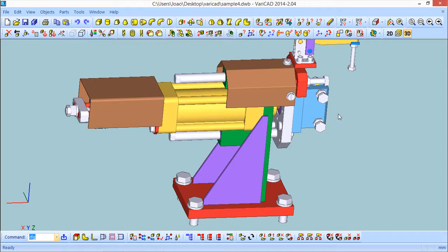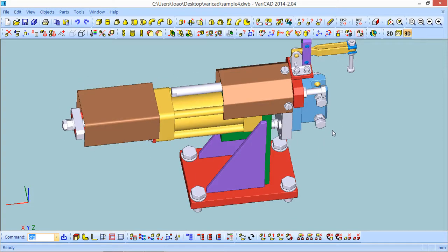The other thing we need to talk about in this lesson is, especially when you have a better machine, not a standard laptop like the one I'm working with, you can set your graphic adapter, especially the anti-aliasing configuration.